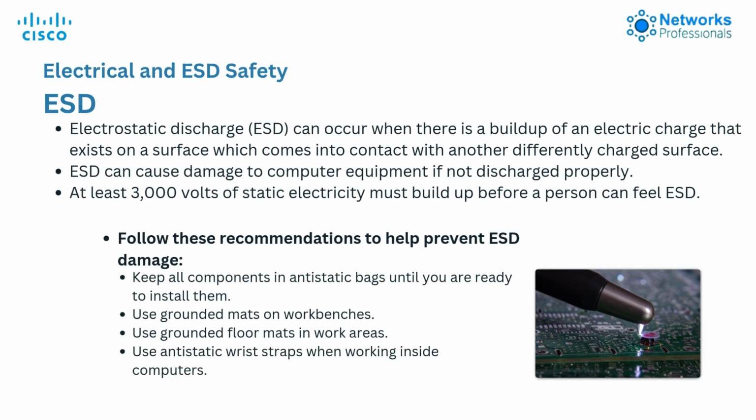Electrical and ESD safety. ESD, electrostatic discharge, can occur when there is a buildup of an electric charge that exists on a surface which comes into contact with another differently charged surface. ESD can cause damage to computer equipment if not discharged properly. At least 3,000 volts of static electricity must build up before a person can feel ESD. Follow these recommendations to help prevent ESD damage.